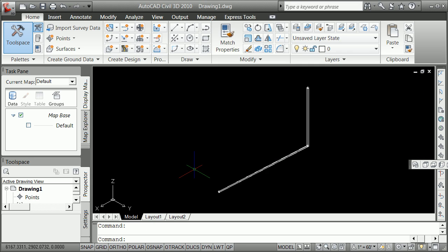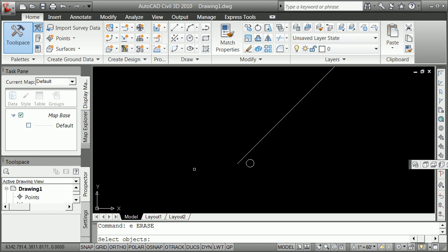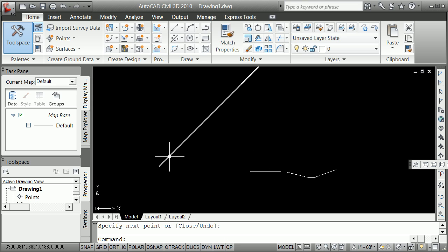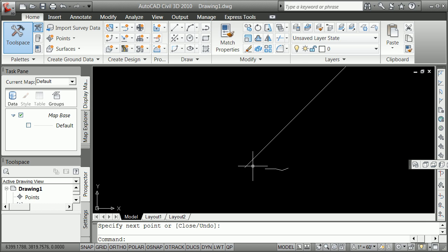So I'm going to do a couple of undos here. Let's try that with a road now. Instead of that, I'm going to make a roadway. I'm going to make my line from here at 12, comma, minus 0.24, at 4, comma, minus 0.16, and then at 8, comma, minus 2, at 2, comma, 0, at 8, comma, plus 3. And I am now going to try to sweep that along this same surface. I'm not going to even make it a polyline. I'll make those individual entities. We'll see how it works.